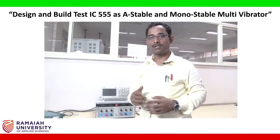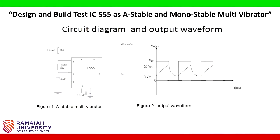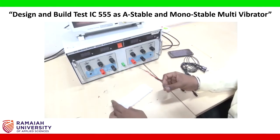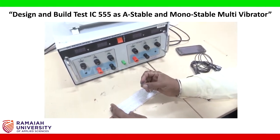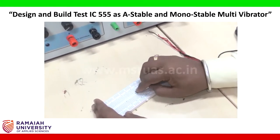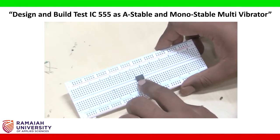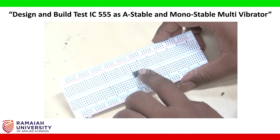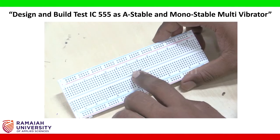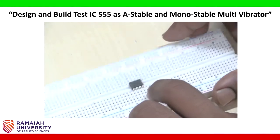Now let us start the circuit connection of astable multivibrator based upon the circuit diagram. Take the breadboard and mount the IC 555 timer on the circuit board like this. See, I mounted the IC 555 on the circuit board. Pins 1, 2, 3, 4 are at the left side, 5, 6, 7, 8 at the right side.